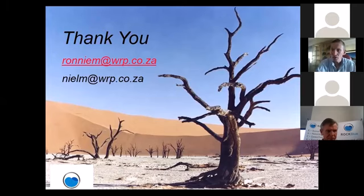And you end up breaching the zone, in which case all your best pressure management experience, all the controllers, even the smartest controller, cannot handle a plumber going round and opening a zone valve. That is by far the biggest problem that we face, not managing the zone valves, keeping those that should be closed, closed, and keeping those in the middle of the zone that should be open, open. As soon as you shut valves in the middle of a zone in order to fight a fire or to fix a leak, you've got to open them all again, or the zone does not operate as it was originally intended. And that is the biggest problem by far that we experience everywhere in the world. First world, third world, developing, undeveloped. It's the same problem everywhere.